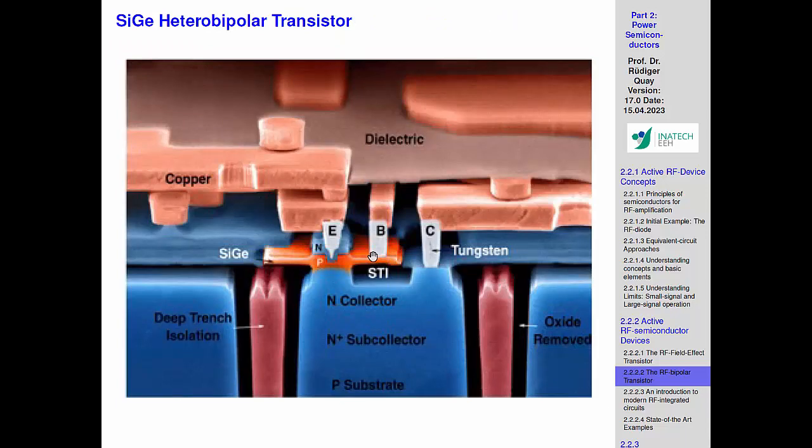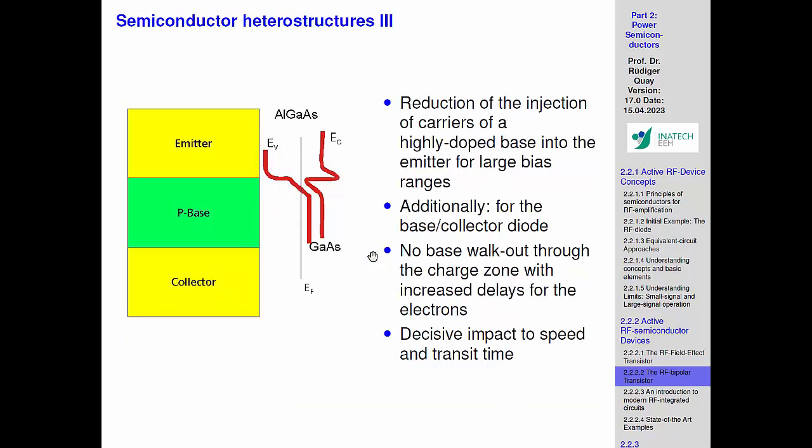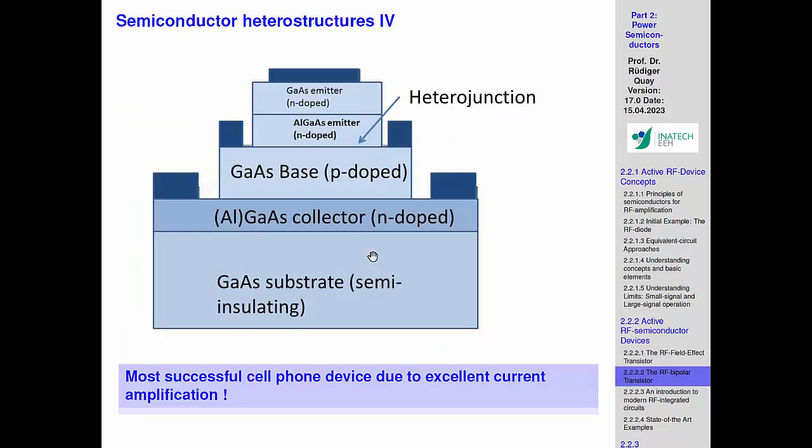This is silicon, yeah. There are also speedy variants of these ones. This is just gallium arsenide, but you can apply the same better materials we used for these HEMTs also to the bipolars, and then you are also getting quite good speeds.